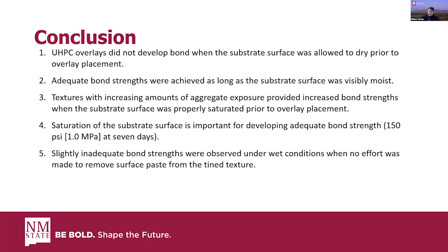Okay, some conclusions from this study. UHPC overlay did not develop bond when the substrate surface was allowed to dry prior to overlay placement. Adequate bond strengths were achieved as long as the substrate surface was visibly moist. Textures with increasing amounts of aggregate exposure provided increased bond strengths when the substrate surface was properly saturated prior to overlay placement. And saturation of the substrate surface is important for developing adequate bond strengths. And again, that adequate bond strength is 150 PSI at 7 days, set by ACI 546.